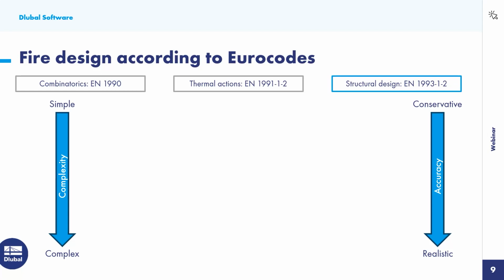The actual design of structural elements is regulated in the respective material-specific Eurocode, such as the Eurocode 3 Part 1-2 for steel construction. In principle, all ECs or Eurocodes distinguish between 3 alternative methods with increasing complexity and accuracy. The simplest design approach is design by tabulated data. This is oftentimes used for fire design of concrete elements, where it is sufficient to choose the suitable dimensions, for example, wall thickness, for a specific fire class. This approach is unfortunately not available for steel structures.